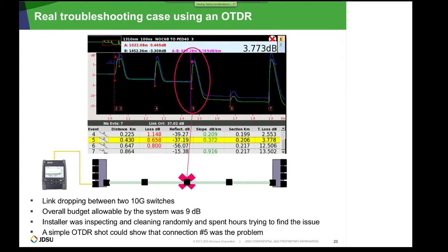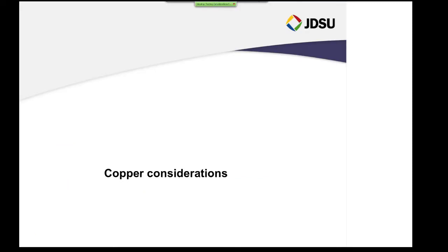Here from the trace you see significant insertion loss, which represents in this case about 8.5 or even more dB per connector. Remember, we discussed that the limit for a connector insertion loss is 0.75 dB. Here we are speaking even about 8.6 dB insertion loss of the connector.